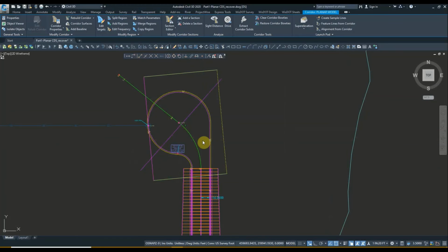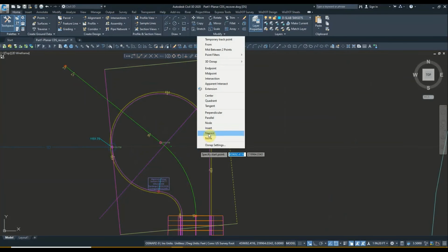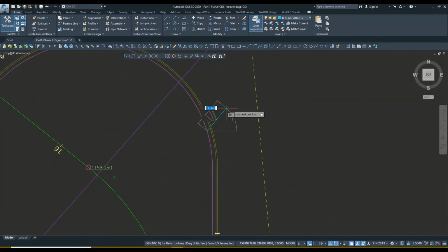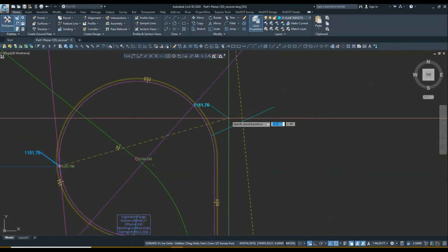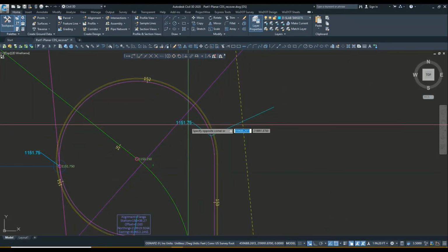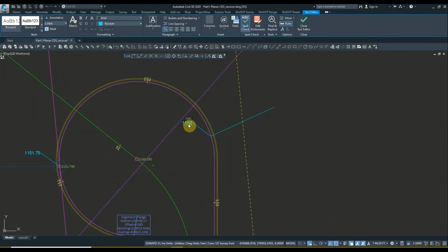but now this looks pretty clean. And what we will do now is we'll select an arbitrary inlet somewhere over here, just put it right there for now, and we will also give it an arbitrary elevation just for this example. We'll select, we can try 1152.